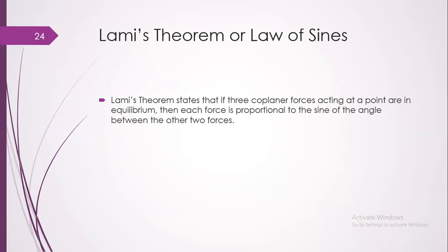Another concept in applied mechanics is Lami's theorem, or the law of sines. Lami's theorem states that if three coplanar forces, coplanar meaning forces in the same plane, act on a point in equilibrium, then each force is proportional to the sine of the angle between the other two forces. So this is Lami's law of sines.